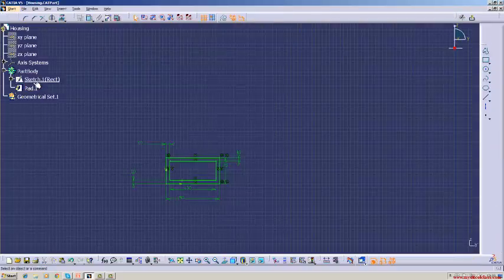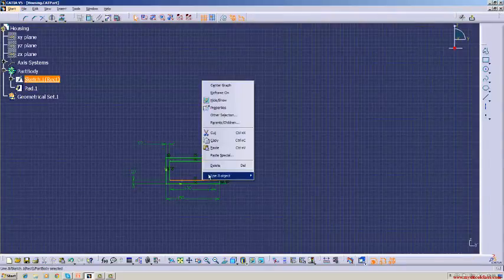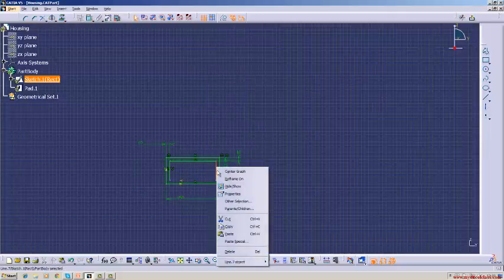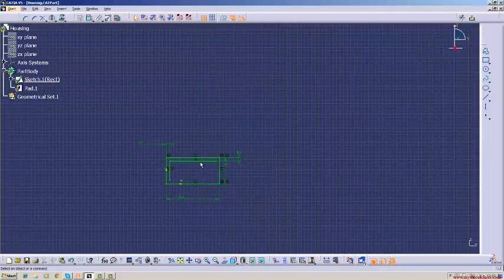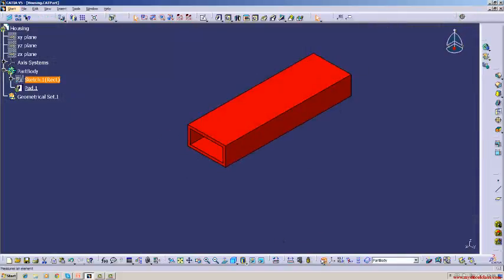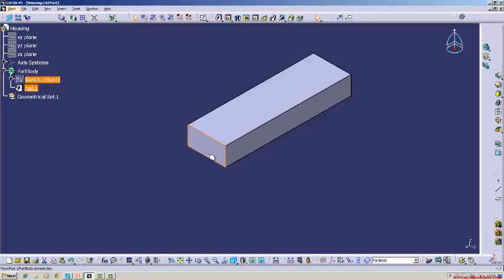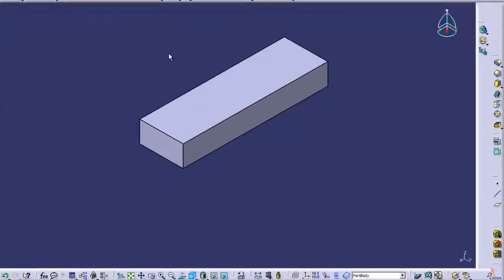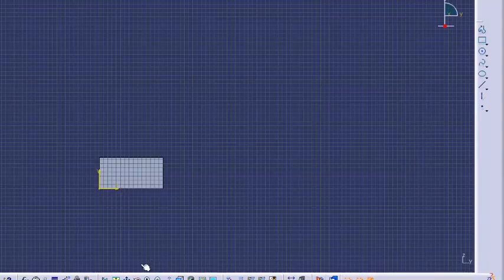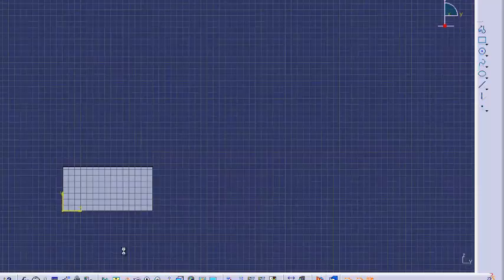So for that, what I do is, I will remove this inside. This is solid. Now we want to create a blind hole inside. Then what we have to do, we have to select the plane. We want from here only. From this face you want to make a blind hole. Select this, and then you can select as usual and make it central.